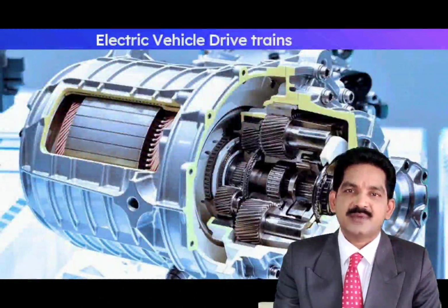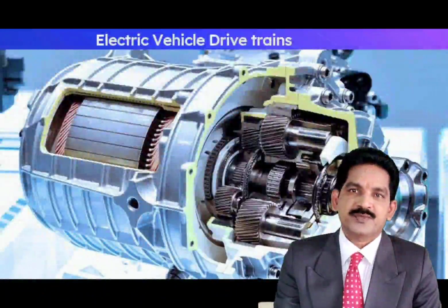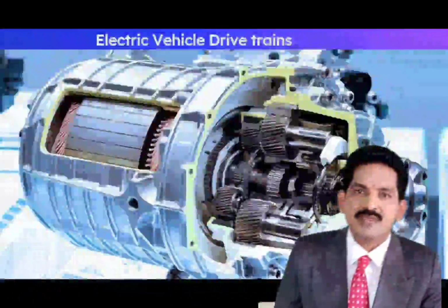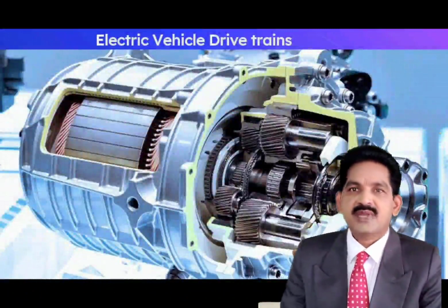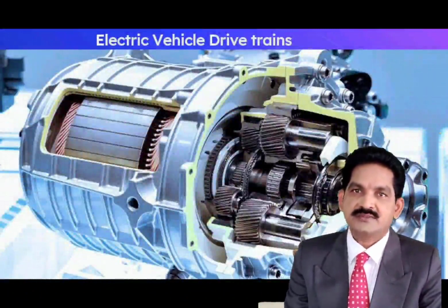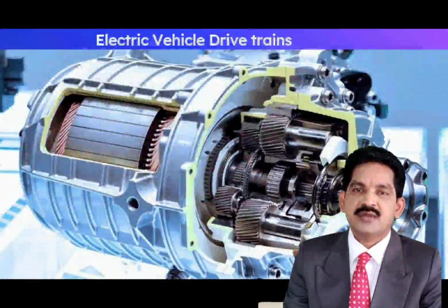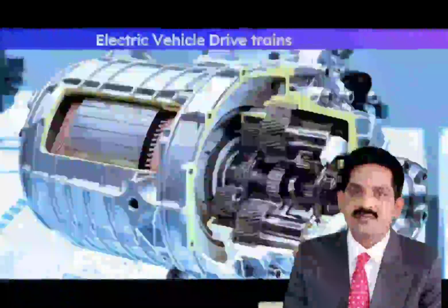The key components like straight gears, helical gears, and housings are common to both types of drivetrain. The main challenges in specializing such components for electric vehicle drivetrains are to deal with the higher torque and speed of rotation that can be realized with electric motors, and the tolerances involved in the precision manufacturing of the transmission